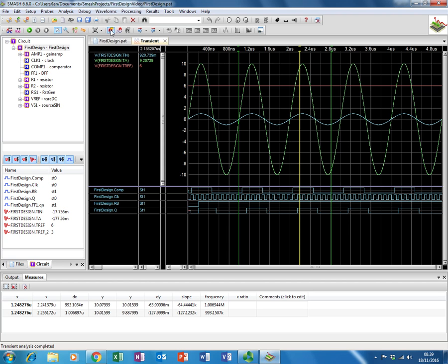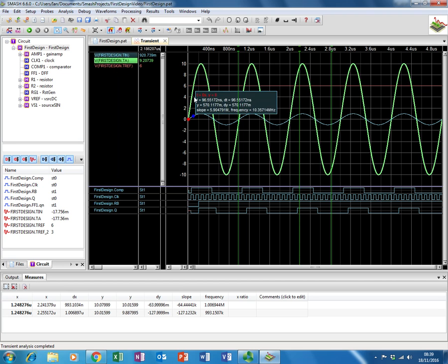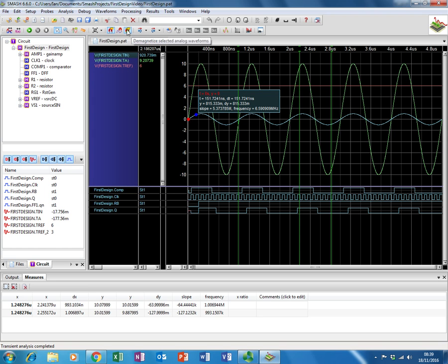Another feature is this magnetize feature, which allows you to follow the value along with a kind of sticky magnetic point. So if I just click on a waveform, this little blue dot allows me to move along a waveform, and I can select any waveform and it'll give me information about that waveform as I move along it and see what's going on in the system. So it's kind of just scraping the surface really of what you can do with this. To stop the magnetization, you have to click on the demagnetize button.